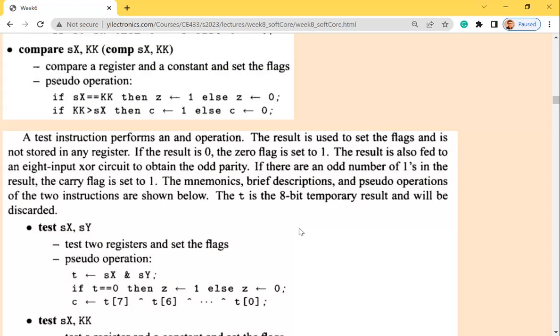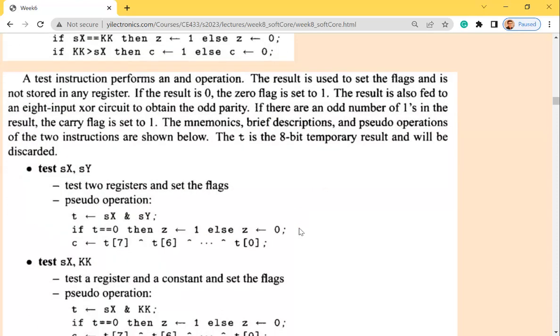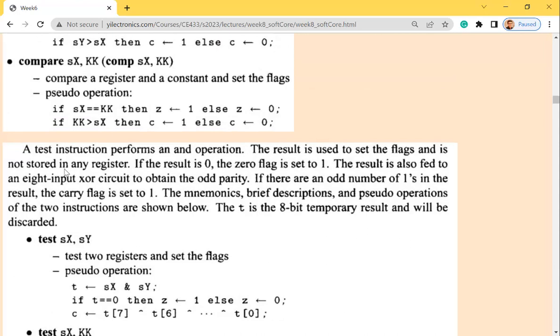If Z is 1, you AND whatever, it's going to still be that thing, right? You can do an AND operation afterwards, and then there's another instruction where you can make a judgment if it is a 0 or not, to jump somewhere else to do other operations. Okay, that's one strategy to implement an if statement.